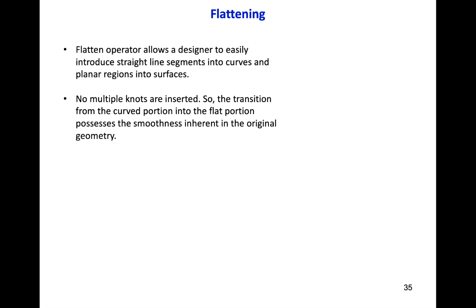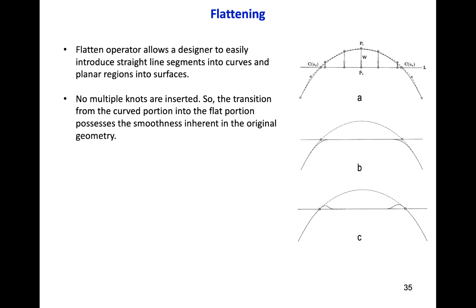Hi everyone, I am Sadman. I will continue from the topic flattening. The flatten operator allows a designer to easily introduce straight line segments into curves and planar regions into surfaces. In flattening, no multiple knots are inserted, so the transition from the curved portion into the flat portion possesses the smoothness inherent in the original geometry.